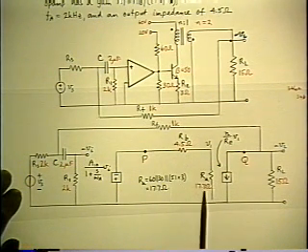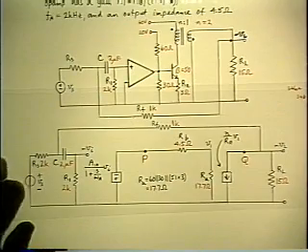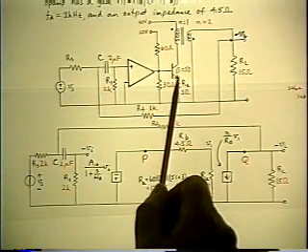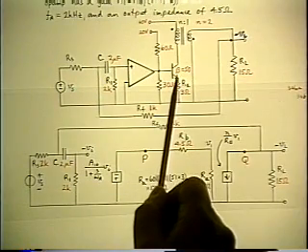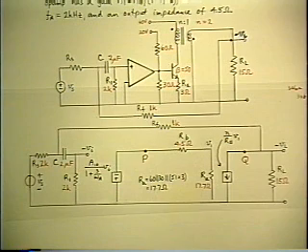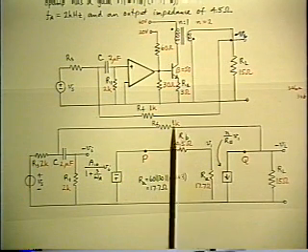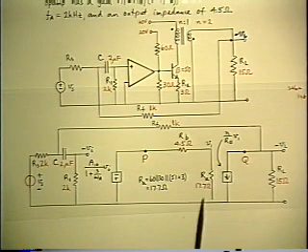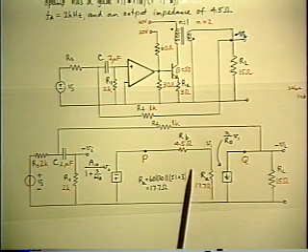That comes to 17.7 ohms. Actually, the internal RE of the transistor should be accounted for as well, but since it's operating at a 1 amp of DC current, its value is only 25 milliohms, which is negligible compared to 3 ohms. So forget that.